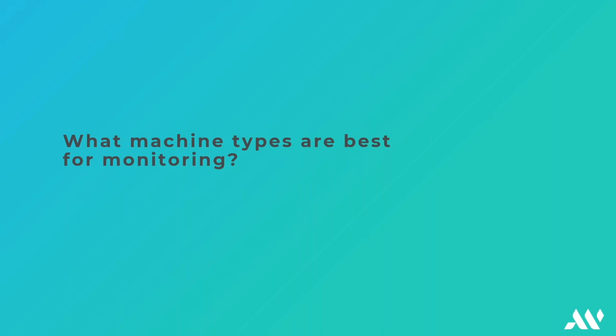Awesome, perfect. And then good FMEA analysis comes into play. Yeah, good point. Eric, can you expand upon that? That's a very involved process. To get that, it's a bunch of if-this-then-that questions that you're asking, mechanically and electrically, with your systems and processes. If this occurs, what effect is that downstream to this machine, to this process? Knowing, obviously, do you have single points of failure within your system where if this goes down, it takes everything down.